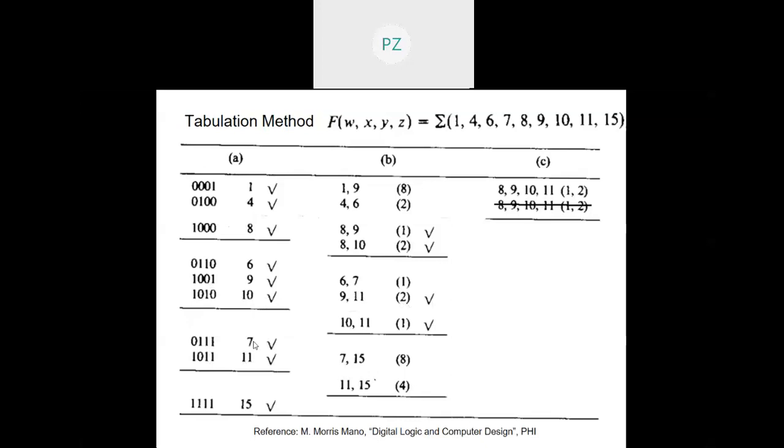10 and 7 cannot be combined because they are varying in more than one place, but 10 11 can be combined, and the bit that gets eliminated corresponds to the weight 1. So 10 11 corresponding to the weight 1, which in effect would be 1 0 1 dash. So either you write 1 0 1 dash, or you write the bit which gets eliminated, right? And so that covers all the combinations in these two groups. Let us consider the next two groups.